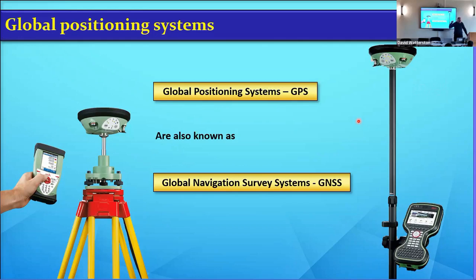One of them was even 0. And I couldn't believe that you could get that accuracy. Because remember, I was using that instrument to get 1 second of arc and 1 millimeter in the distance. So as far as I was concerned, it was very accurate. But this GPS system got it down to a few millimeters. And it's basically talking to bits of metal junk in the sky. It was just unbelievable.